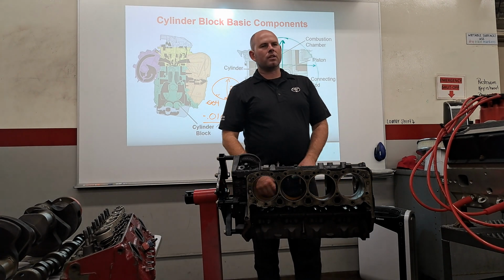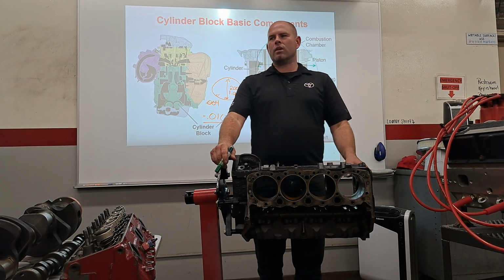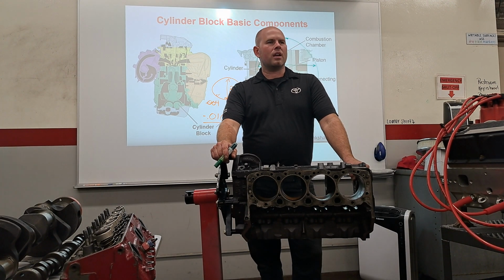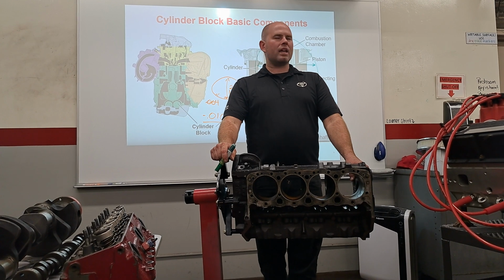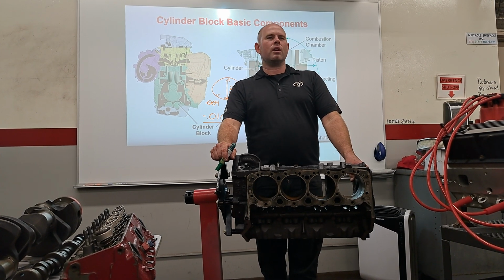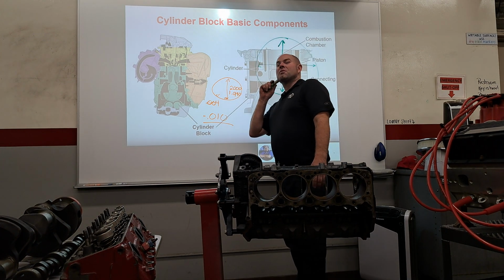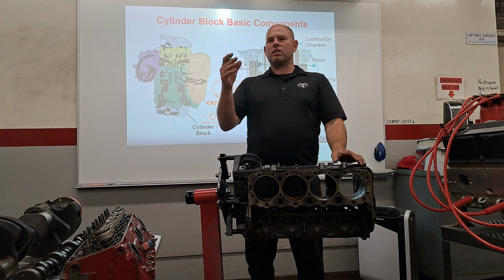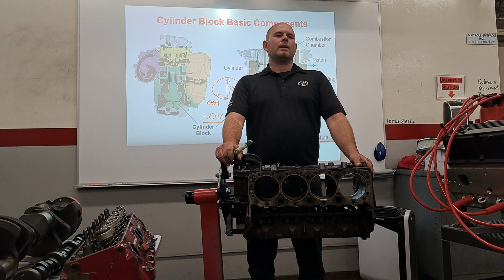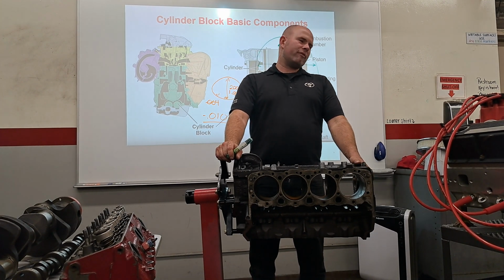So how out-of-round can you get? Typically anything 1,000th or more, that's it, you're done. You can't see that. You have to measure that. If you don't measure that, you're just guessing. You might as well be rebuilding the engine in your garage with your purple Crocs. Make sense? Not to say there's anything wrong with that, but to really do it right, you need to have all the equipment. It's probably not going to happen in the garage over some adult beverages while football games going in the background and